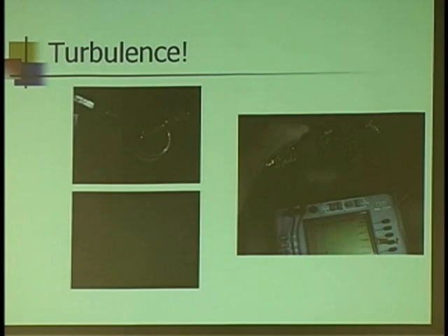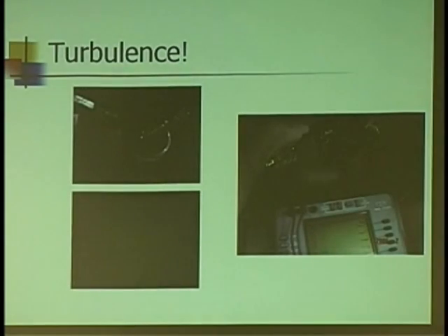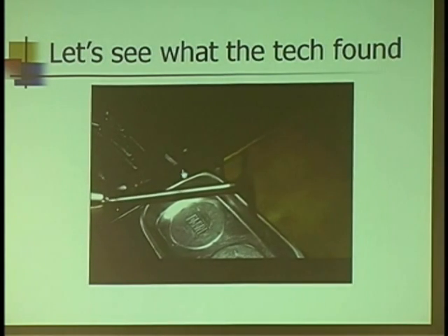But once I started seeing these in the pattern, and there were more than one, I went back to the tech. I said, you know what? Your gut instinct was right all along. These valves are not sealing. I hate to tell you this, the heads have to come back off. You take them back to the machine shop and tell them they were wrong. And when you do, save the old stuff so I can see it. I came back about a week later, and this is what he showed me.